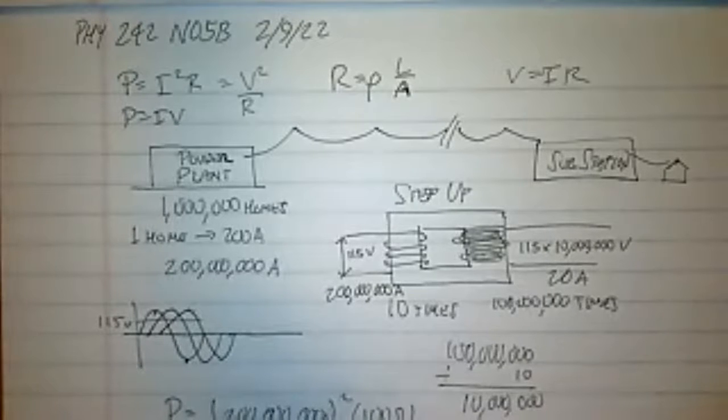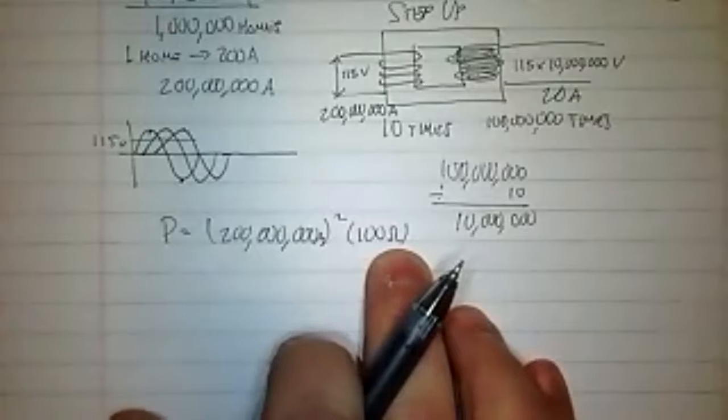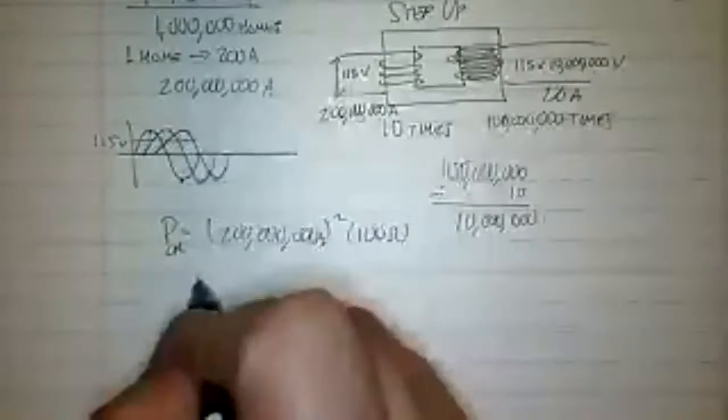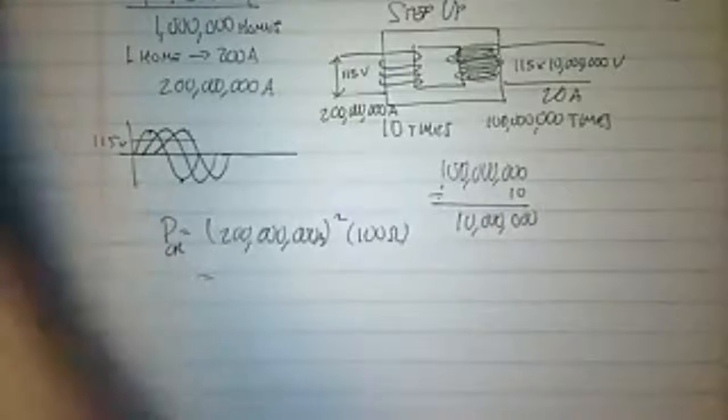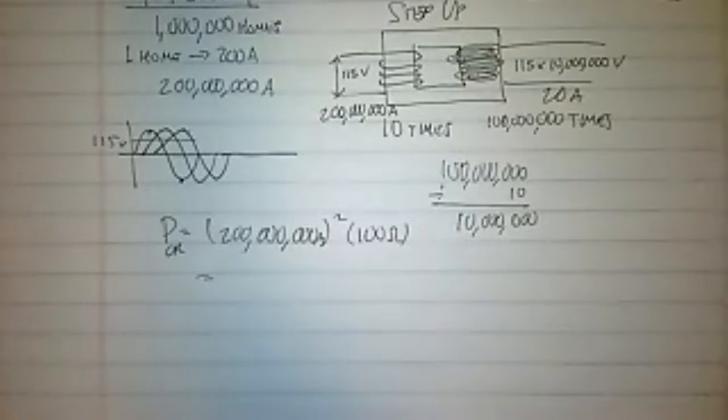As we saw, we did 200 kilometers yesterday, and we got like 6 ohms for copper and like 10 ohms for aluminum. So it's probably not unreasonable to have on the order of a couple hundred ohms for the resistance. So this is original, and you get 2 million times 100, or excuse me, 200 million.